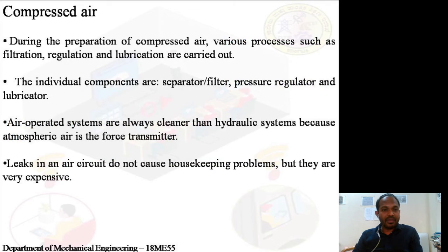Now I am just talking about this compressed air. During the preparation of compressed air, various processing such as filtration, regulation and lubrication are carried out. Filtration, regulation and lubrication are all carried out. The individual components are a separator or a filter, the pressure regulator and the lubricators.